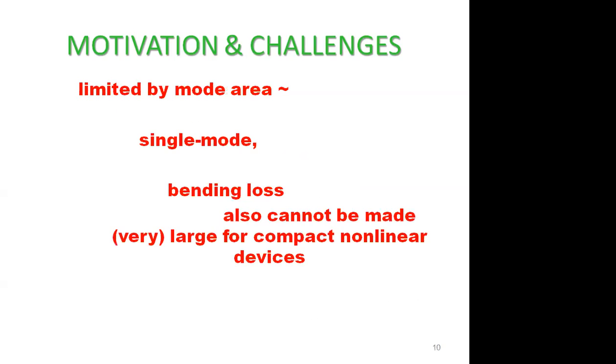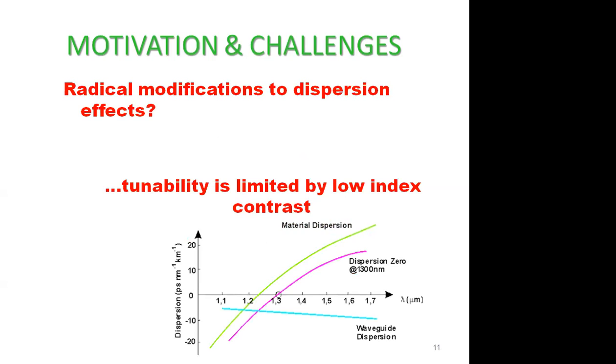Now disadvantage is what? We can shift this 1300 zero dispersion, you can shift this to any value above 1.3. You can design a fiber in such a way that zero dispersion can be shifted to 1.4, 1.5, 1.6, any value you can shift it. So for that reason, at 1550, loss is less, and we can shift that zero dispersion from 1.3 to any value. For that reason, we'll use 1550.